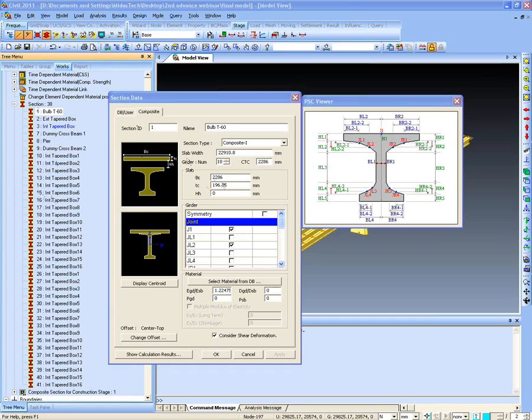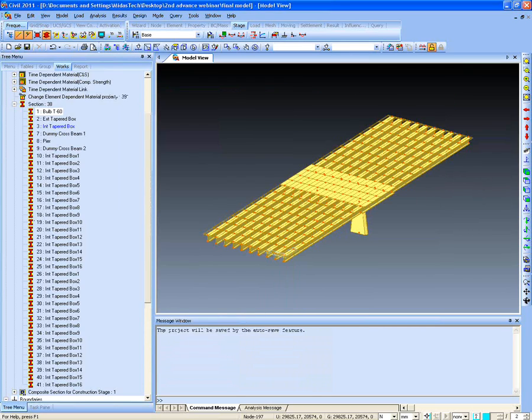For the grillage model, the user must enter the data for one section only. So slab width would be the width for a section and the girder number will be 1 having CTC 0. I hope it answers your question, Mr. Salius.